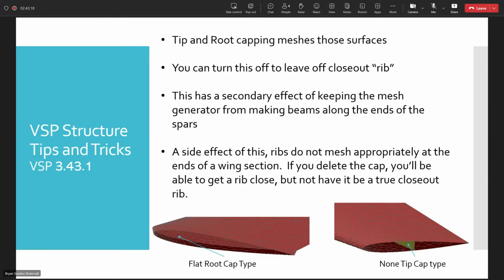There are some implications there if you add beams along spars, where it will add beams on the vertical portion of the shear web at that center line. If you turn it off, then it won't do that. So that's kind of helpful. It's not a big deal.